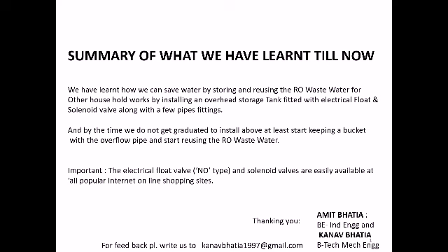This is the last slide showing the summary of what we have learned till now. Until we graduate to installing an overhead storage tank fitted with electrical float and solenoid valve, at least we should start keeping a bucket with an overflow pipe and start reusing the RO wastewater. Moreover, it's not very difficult, rather it's very easy to go in for the overhead storage tank with an automatic float and solenoid valve, since these float valves and solenoid valves are easily available at all popular online shopping sites.